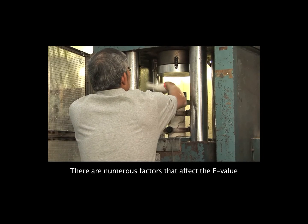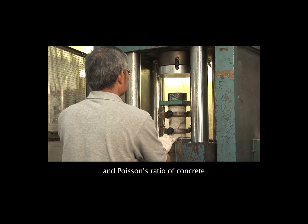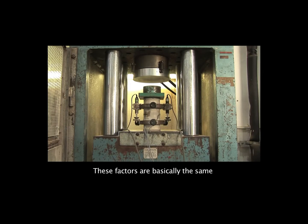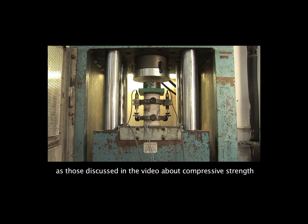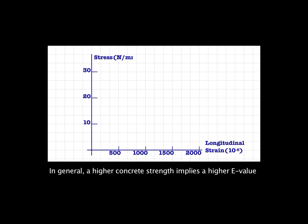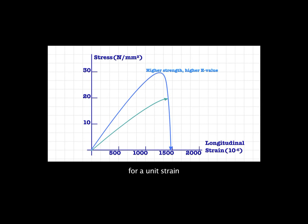There are numerous factors that affect the E value and Poisson's ratio of concrete. These factors are basically the same as those discussed in the video about compressive strength. In general, a higher concrete strength implies a higher E value, which means that the concrete can take a higher stress level for a unit strain.